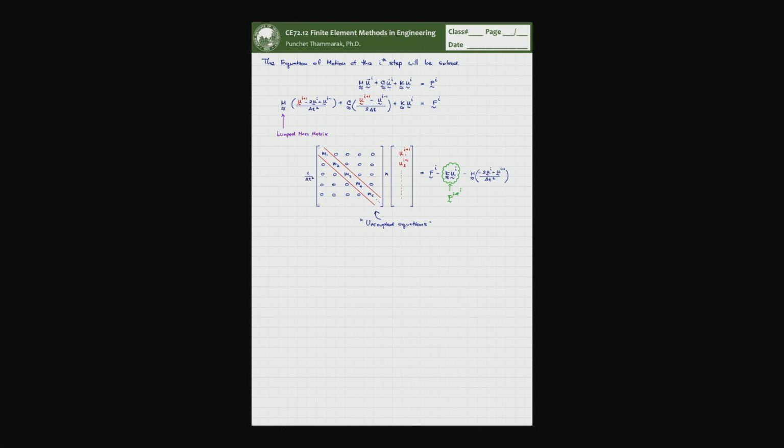So the time stepping size has to be extremely small to make this scheme possible to use. So good discretization in space and good discretization in time is generally the requirement in order to use the simplified scheme. Okay. What else?